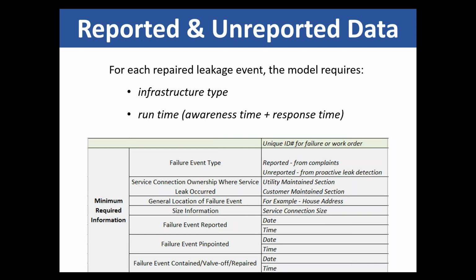It's important to note that it should be the same audit period as your water audit so that the volumes all correspond. So you want to report the number of leaks and the infrastructure type. Was this a leak on a main? Was it a leak on a service connection? Was it in a meter box? Did somebody share a hydrant? Those sorts of questions. You'll also want to report that leak's runtime, from the moment it entered your database and somebody called it in and said, there's water running down the road, when you became aware of it, to when you contained the flow.